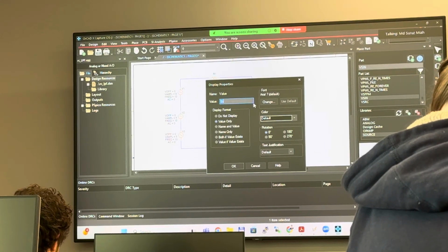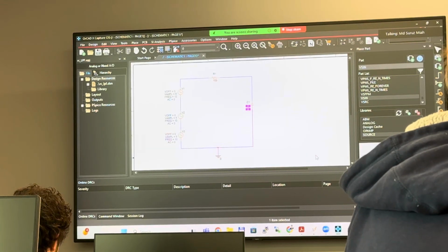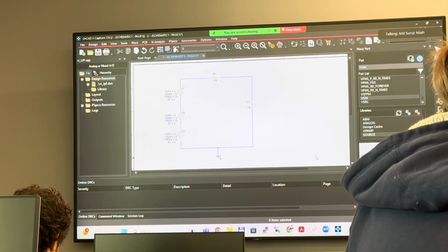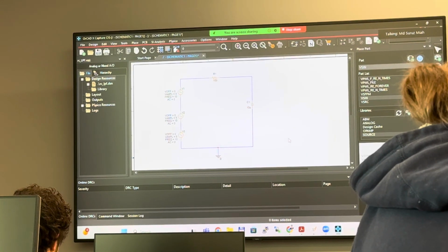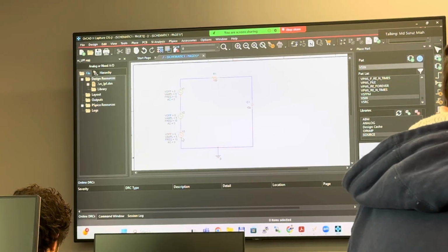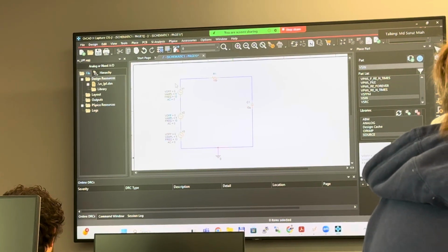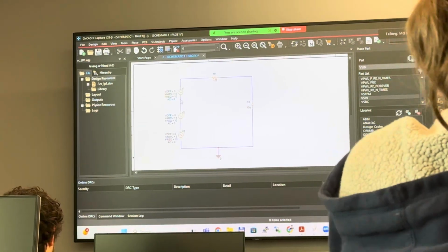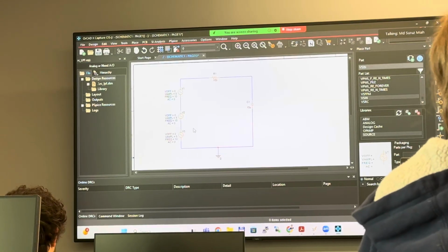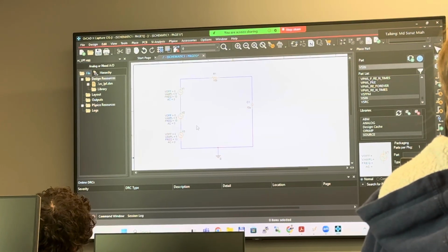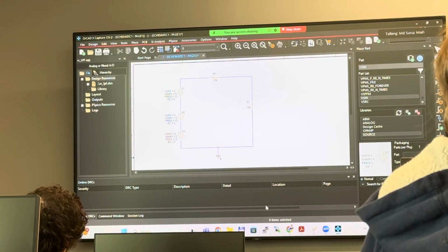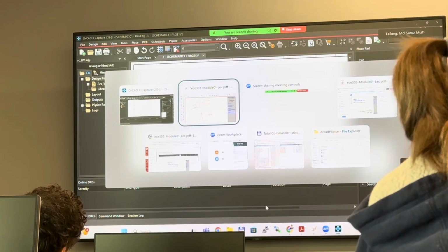So you simply write 10 U, so that is going to be 10 microfarad. So we have configured all the sources, and all these sources will be added together and create an input VI in our case.